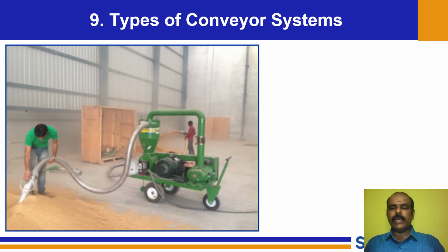But one thing we need to go ahead with, all these products whatever we use should be free from wetness. It should be completely dry, then only it nicely mixes with air, then it goes on. If it is wet, no, this system will not work. So that's what I have been emphasizing. Based on the nature of the stock item, we shall decide upon the conveyor system.